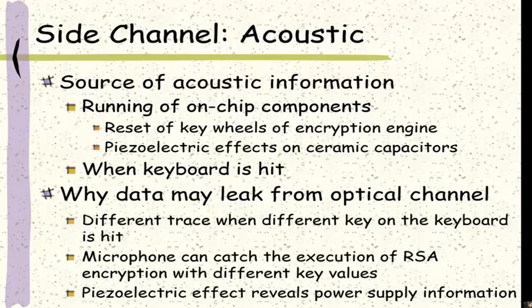For instance, it was reported that on a home-built PC with RSA encryption implemented, when a microphone is placed close by, it can capture the acoustic information to tell when the RSA encryption algorithm is running. Furthermore, the runs of the RSA with different key values give different acoustic traces. It is speculated that the acoustic emission is the result of the piezoelectric properties of the ceramic capacitors used on the motherboard of this system. This is related to the power and the current draw on the chip.